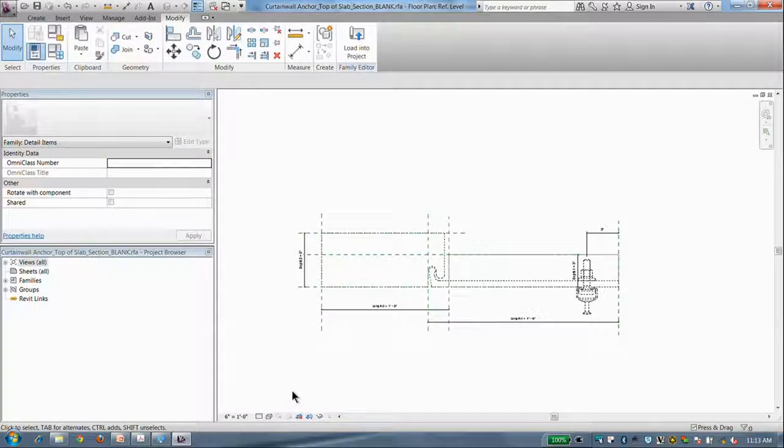So, it's kind of stuff like that. Now, it took us 5 or 6 minutes to do this? I kind of know what's going on when I show this off to somebody. Usually, we'll spend like 20 minutes trying stuff, and I'll have them create something similar. And they start learning the rules about how these constraints work and the power of it. But I rarely will start them off anything more complicated than this, right? It's 4 parameters, about 6 reference planes, and I just keep it at that level because otherwise, if I get too parametric with it, they abandon it, they don't use it. So instead of creating a parametric one where you can adjust any size you want, they end up creating 20 of these, 20 files they have to maintain, which is clearly not the most efficient way of doing it.